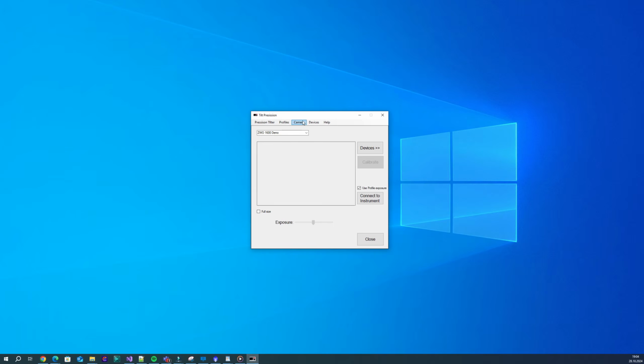The application has now to be connected to the instrument. First, select Instrument Camera in the Camera menu. Then, since this is the first time calibration on this setup, uncheck Use Profile Exposure so that ideal conditions are calculated. Finally, press the Connect button.